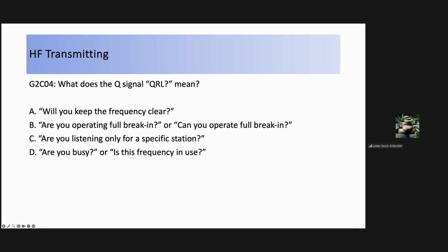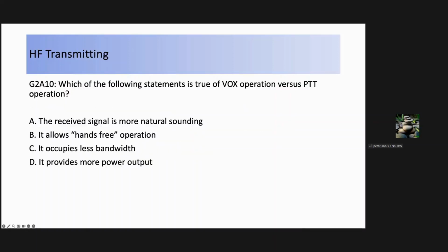So transmitting questions. What does the Q signal QRL mean? Are you busy, or is this frequency in use? Which of the following statements is true of voice-operated operation versus PTT operation? It allows hands-free operation, so you don't need a finger or a foot pushing the push-to-talk button.